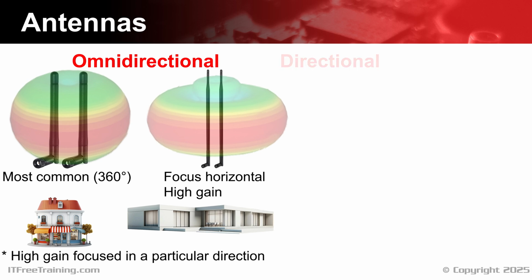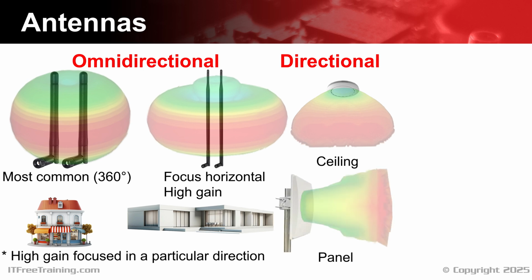There are also other Wi-Fi antennas designed to transmit in a particular direction. For example, ceiling antennas. Due to their elevated position, this allows the signal to travel further and penetrate obstacles more effectively in certain circumstances. They work best when placed in an elevated position that is unobstructed. There are also panel antennas which broadcast horizontally in one direction. These are good for outdoor areas like parks, streets, corridors, or tunnels where you want to provide coverage in a particular area. They can also help reduce interference since they are sending all the signals in one direction.